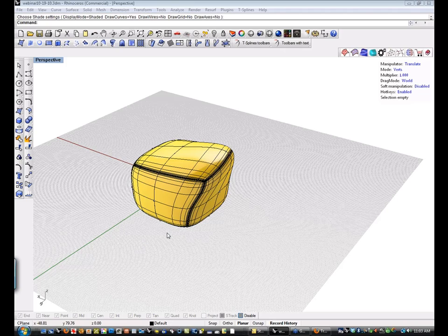But if you go back and try to modify the history, they lose their history when you do the Boolean operation. So I think what you're getting at is, say I took two spheres and Boolean them together, would the history translate from the T-splines to the NURBS through the Boolean, so that if I modified the T-splines, the Boolean would update? No, it won't, because it loses the historical connection once you do the Boolean. That would be sweet, though, if it did that.